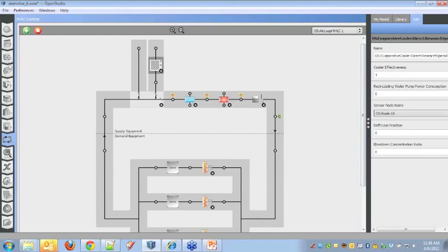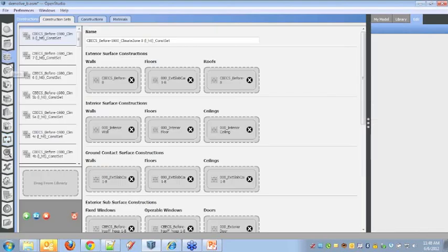So let me jump to constructions here. And please unmute if you do have questions, but like I said, we can go back to those. So I'm going to purge some unused objects out of this model. Basically, the templates were preloaded with construction sets for all these different vintages and climate zones. And in the end, I've put my building in a single climate zone for the 2009 vintage. So it'll take just a second to clear out these unused ones.